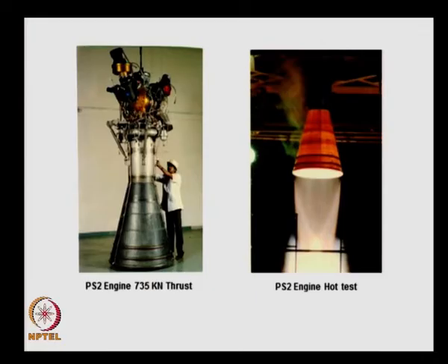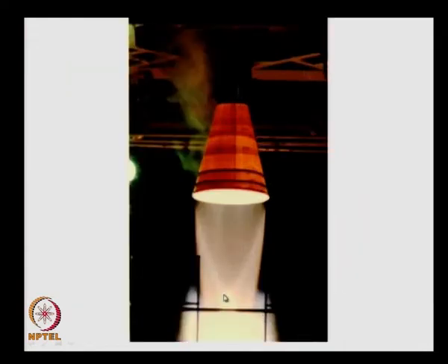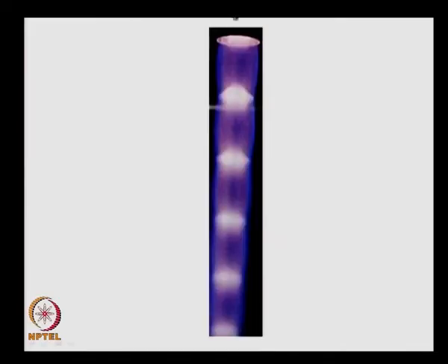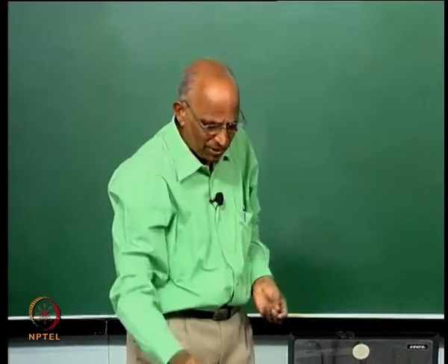Yes, see, in this case we had the nozzle, we had the oblique shock wave, we would have got some shock diamonds a little later as is shown here, but in this particular test some cooling of the plume was done, therefore it is not visible. This is a test wherein you have the exhaust of the nozzle, and you have one shock diamond, another shock diamond, and it keeps on going. In an inviscid flow you could have an infinite number of these diamonds, but with viscosity there is some dissipation.